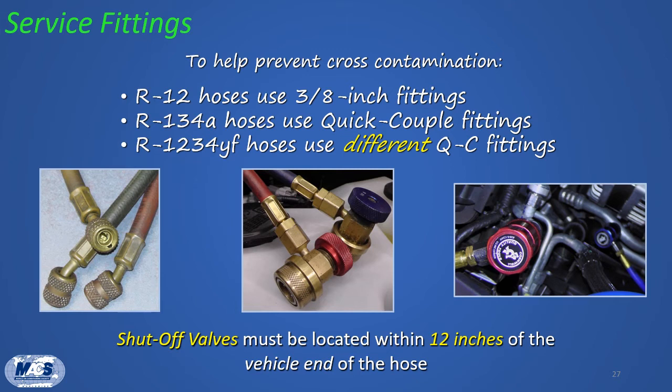There's also a rule that says that shutoff valves have to be located within 12 inches of the vehicle end of the hose. Now, most of your service adapters today have the shutoff valve located directly at the connector itself. But according to the rule, it has to be within 12 inches.